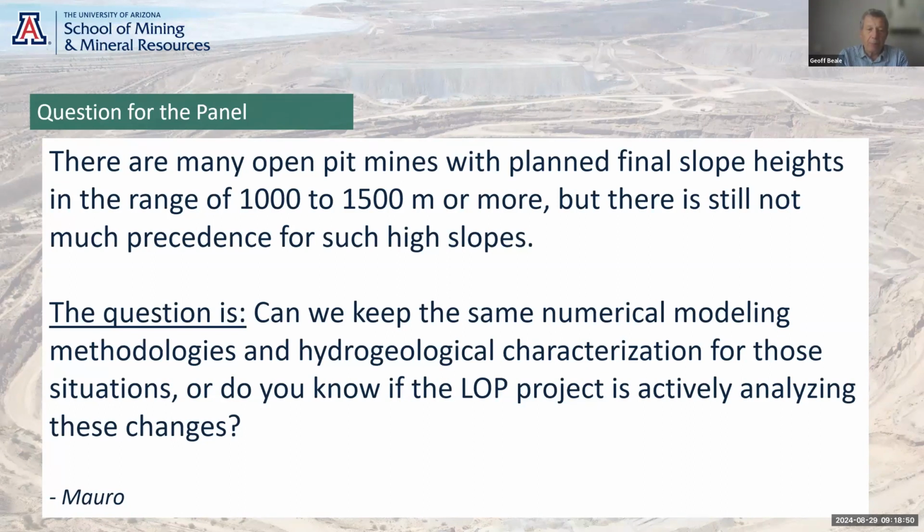For very large pits or very high slopes, the stresses in the slope can change, and an approach that many of the big pits have either considered or implemented is the idea of a drainage tunnel, because the consequences of an overall slope failure are that much greater if you've got a bigger slope.